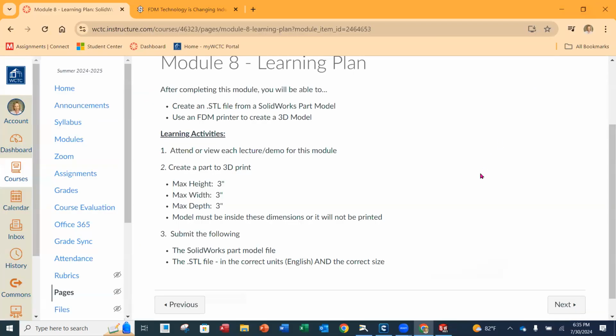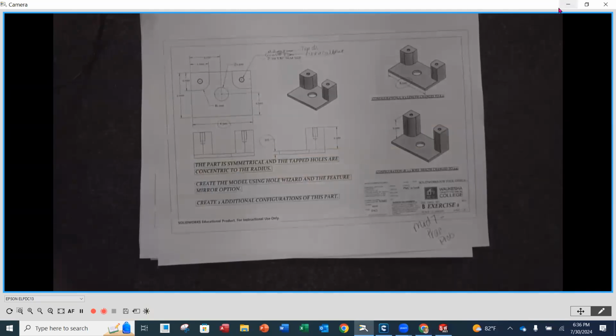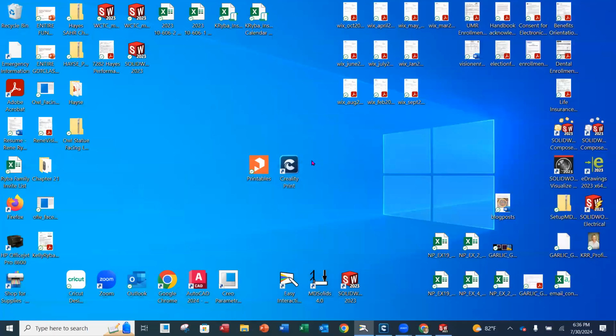All right, what I'm going to do now is slice it. So as we saw earlier, when the 3D printer creates this part, it creates it layer by layer by layer. So right now, this STL file took my solid model and put it in this STL format. It's still a solid model, but we saw those triangles. Now what we need to do is assign what's going on each one of those layers. And that's where we need what we call a slicer. We're going to slice this model up now into its individual layers so that it can write the G code. Yes, G code. You guys are familiar with G code,